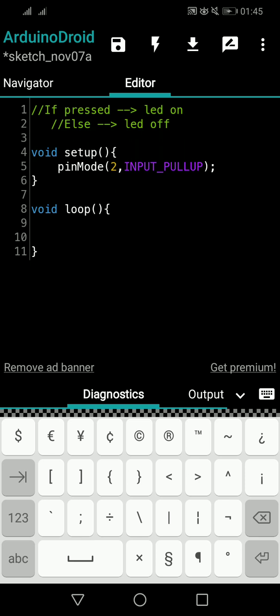So when you press the push button, pin number 2 will become digital input ground. If you take your hand off the switch, then it will be +5. So you know those things. If you don't understand what I am talking about, you have to go and watch the digital input parts of this tutorial series. Then you will understand what I am talking about.